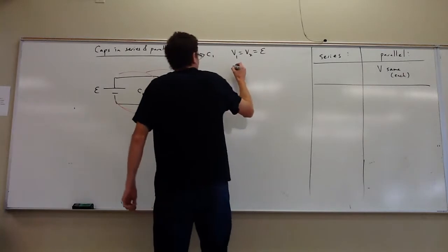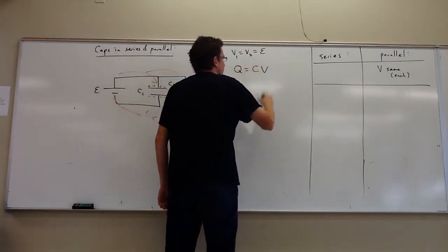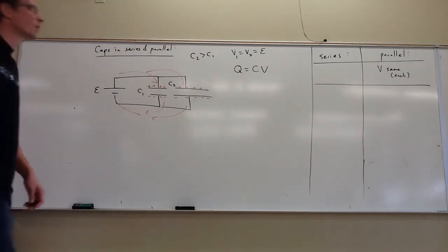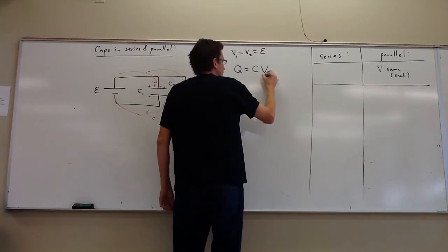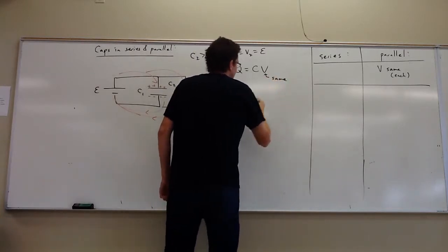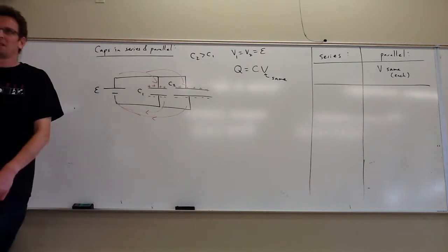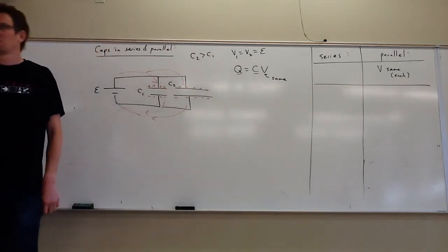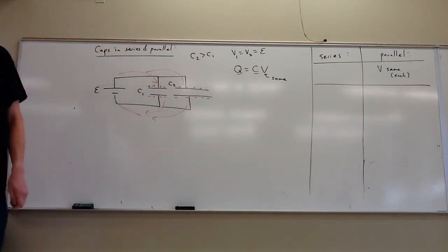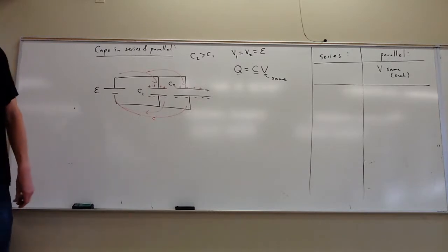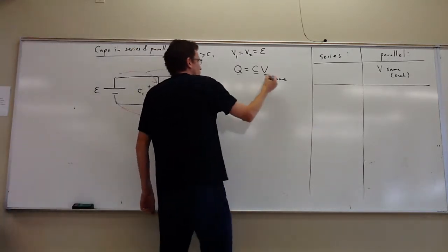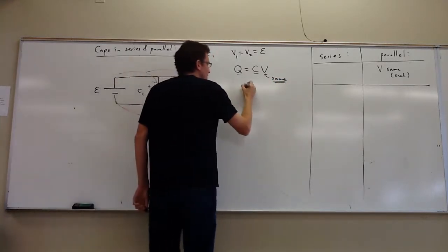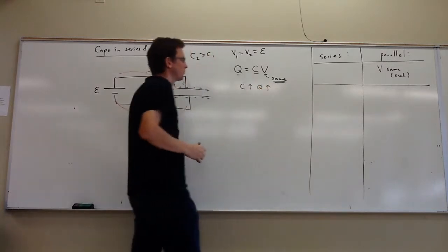So, let's talk about charge though. Q equals CV. I'm just inverting the capacitance formula to solve for Q. And I've just said that the voltage is the same, but if the capacitances are not, will the charge be? No. In fact, which capacitor will get more charge? The second one, exactly. So for the same voltage drop, if it's a better capacitor, it'll get more charge.